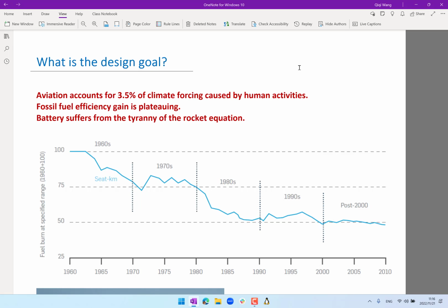Of course, you can increase the span to counter the increased lift, but increasing span would also increase the amount of area, and also increase the structure weight. So additional skin friction drag and yet additional battery. So this compounds, making using battery to complete a long flight infeasible. Short flights are fine.